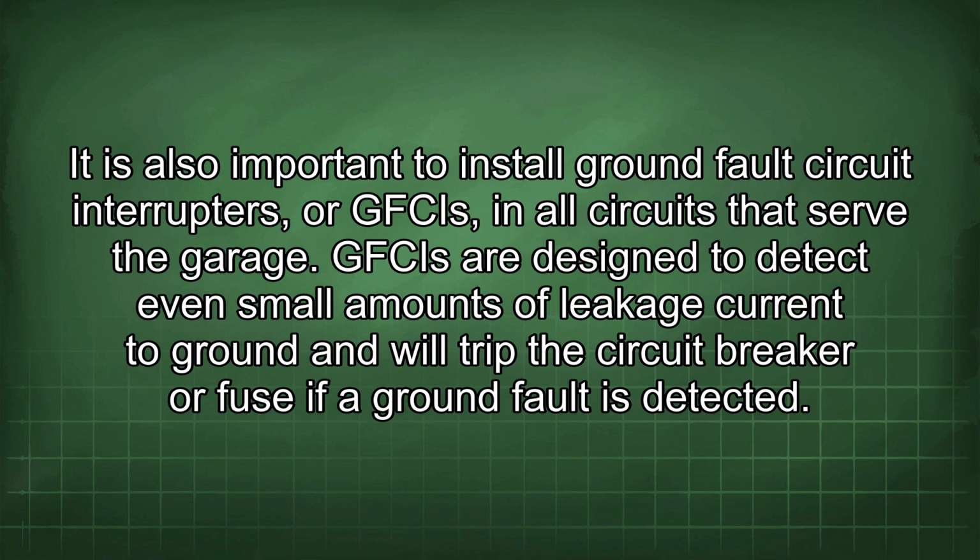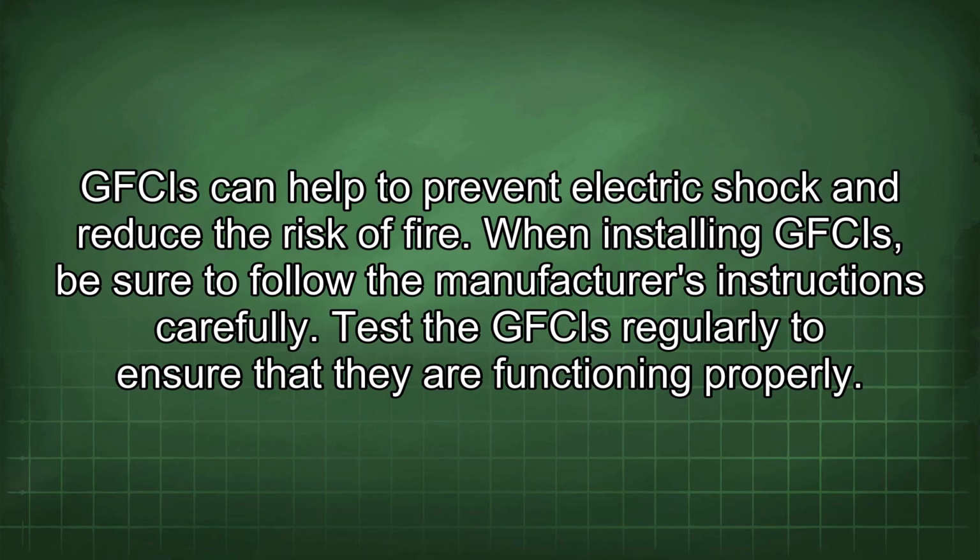It is also important to install ground fault circuit interrupters, or GFCIs, in all circuits that serve the garage. GFCIs are designed to detect even small amounts of leakage current to ground and will trip the circuit breaker or fuse if a ground fault is detected. GFCIs can help to prevent electric shock and reduce the risk of fire. When installing GFCIs, be sure to follow the manufacturer's instructions carefully. Test the GFCIs regularly to ensure that they are functioning properly.